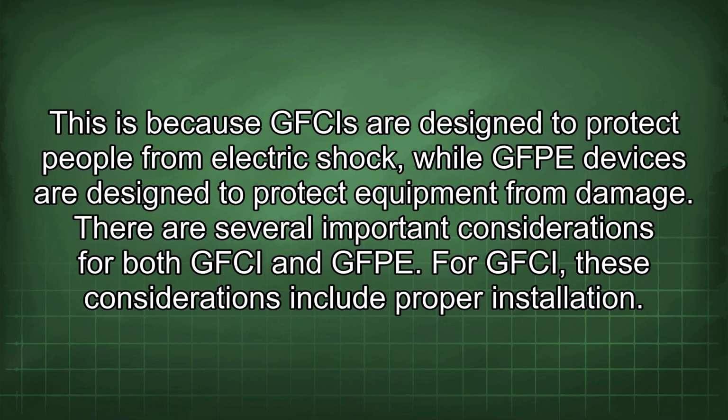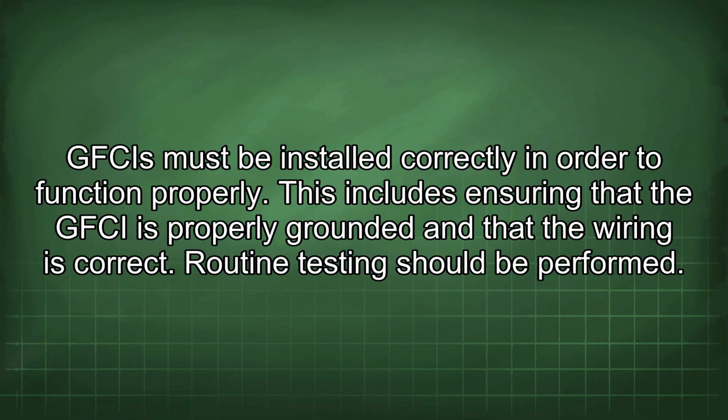For GFCI, these considerations include proper installation. GFCIs must be installed correctly in order to function properly. This includes ensuring that the GFCI is properly grounded and that the wiring is correct.